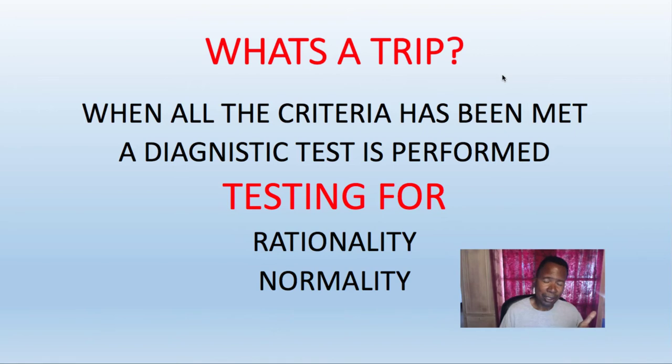A trip, you heard me say the word trip. A trip is not like you think. You don't take your car, drive it to the supermarket, and come back, and call that a trip. No. A trip has certain enable criteria for each monitor to run, and every code has a monitor. When all the criteria have been met, a diagnostic test is performed.